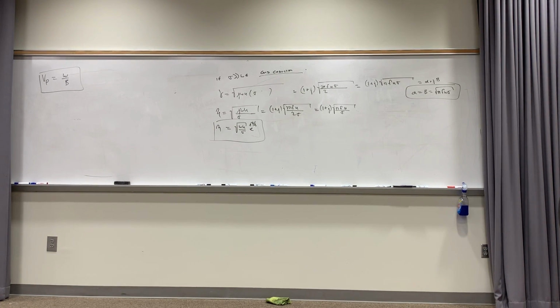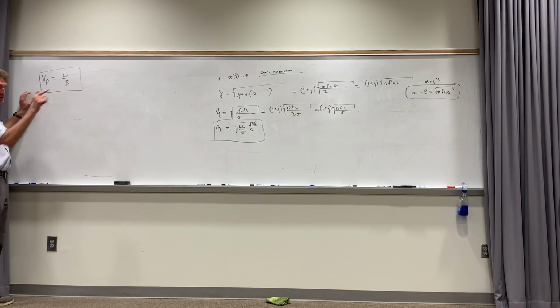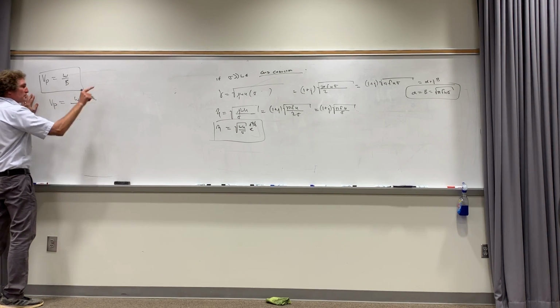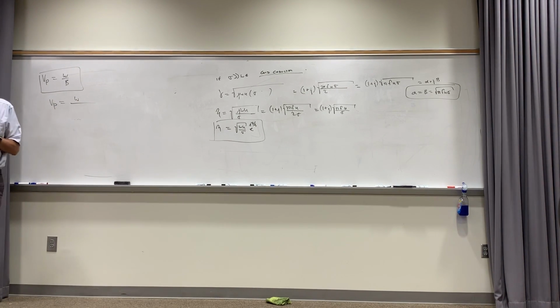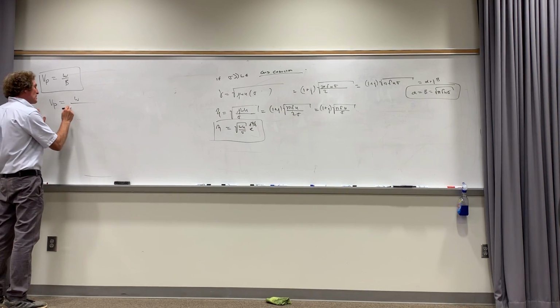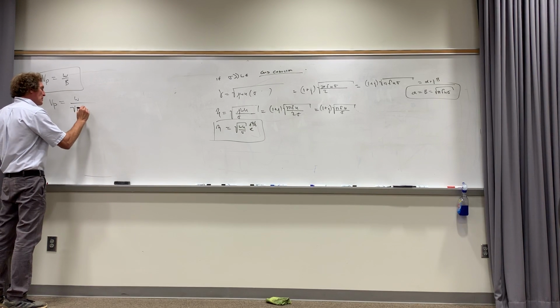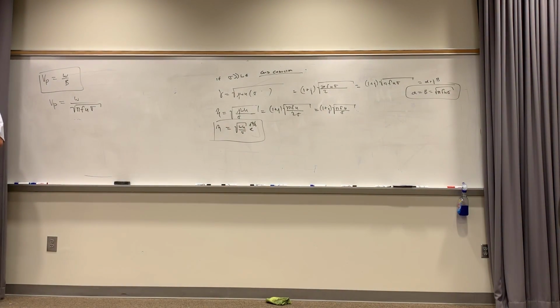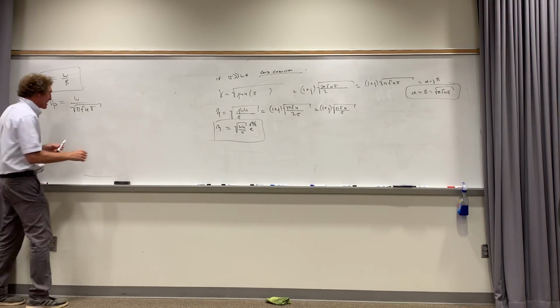Trust me on this. All right, now, what's the phase velocity for metals or good conductors? It's omega, but what's beta? Look over there. Can you read it? Somebody. Square root of pi times f times mu times sigma. Right. Now, watch. I want to show you how slow a wave propagates into the metal. Not on the surface of the metal, but into the metal.